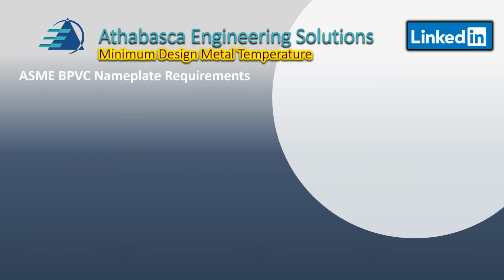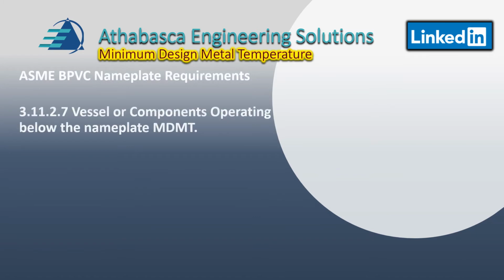So there are a few other rules to keep in mind with the Boiler and Pressure Vessel Code nameplate requirements: vessels or components operating below the MDMT. Let's talk about that. Vessels or components may be operated colder than the MDMT stamped on the nameplate if, and this is found in section 3.11.7 for more detail, the provisions of 3.11.2 are met.